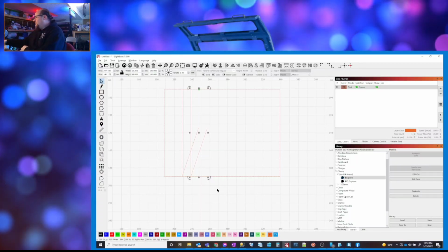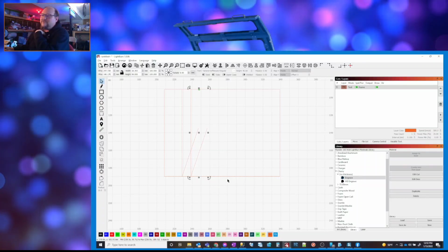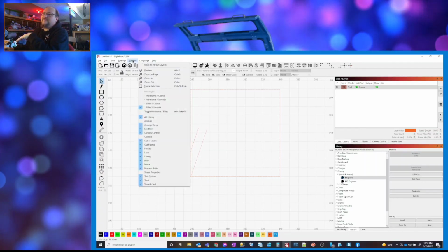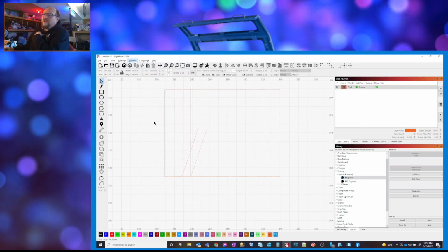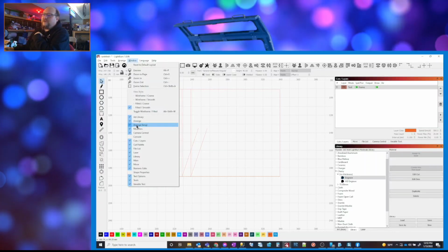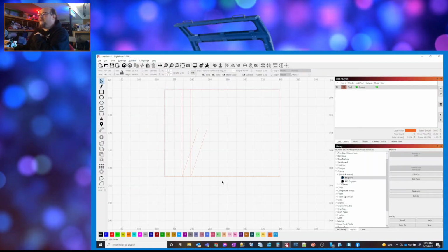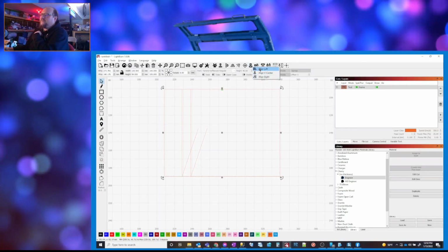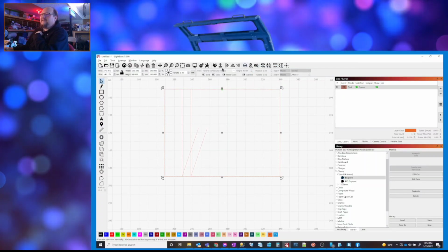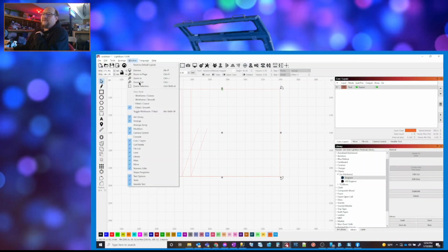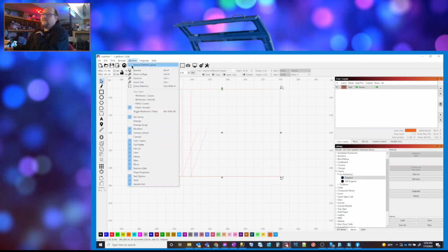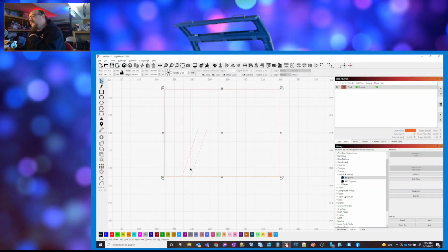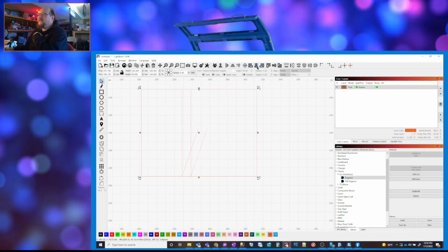The other thing is that I don't see a lot of people doing. I don't understand why LightBurn comes defaulted this way. But if you look under Window, it will have Arrange on, and it will have Arrange Long off. Now, Arrange gives you a few options for arranging things, and then the rest of these you have to drop down to do. I hate that. Absolutely hate it. So I turn that one off, and I turn the long one on, because it gives me quick access to each of those individually. So let's say I wanted to center these up. I could quickly do that.